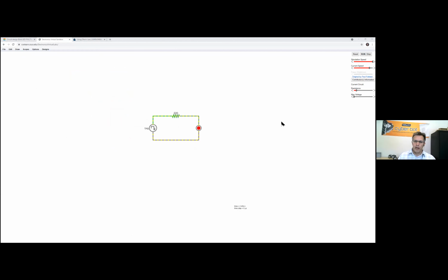And so here is an example where basically instead of the microbit, we're just adding and configuring a little voltage source. And you can go in there and say, I want a square wave with 75% duty cycle and that kind of stuff.